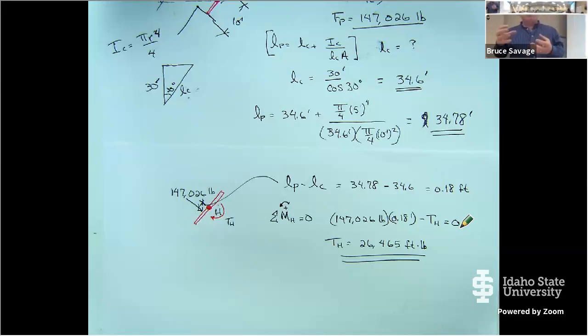So they've used that same principle for these high head valves, where these discs have teeth around the entire side, and the teeth mesh with each other. When you open the valve, those teeth get farther and farther apart. The teeth are arranged in such a way that the teeth on the outside are bigger than the teeth on the inside. Or when I say bigger, they're more separated.